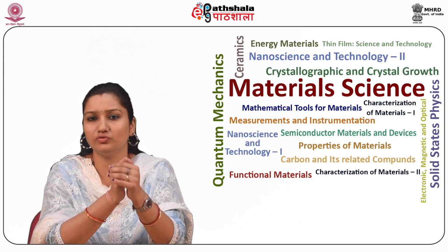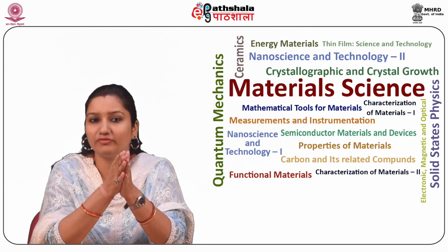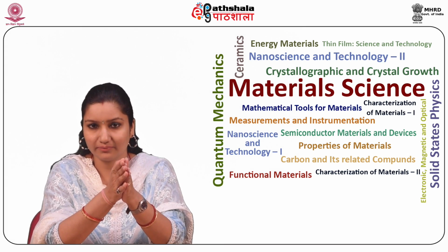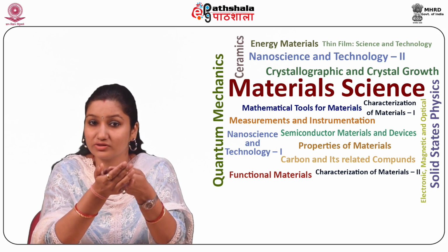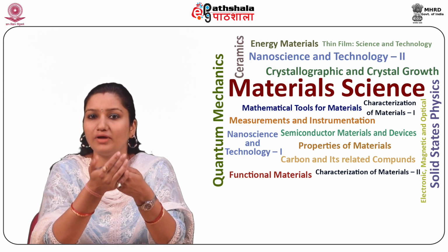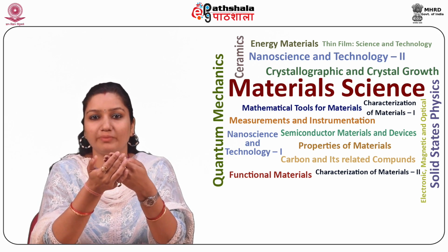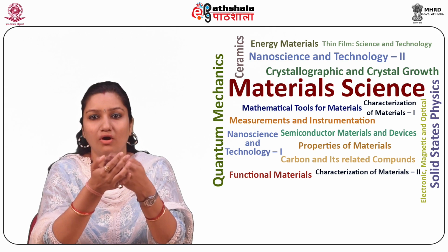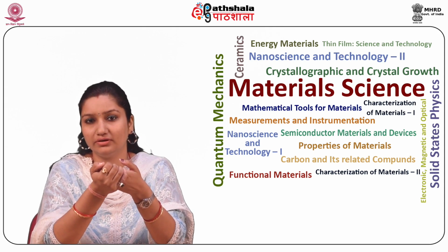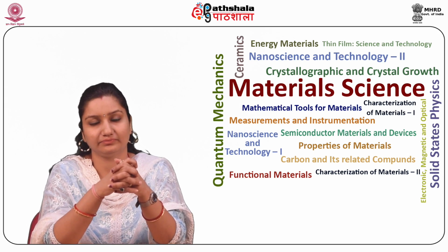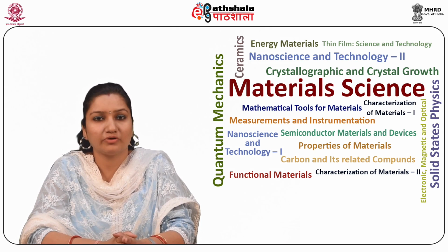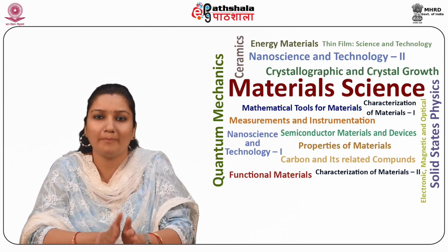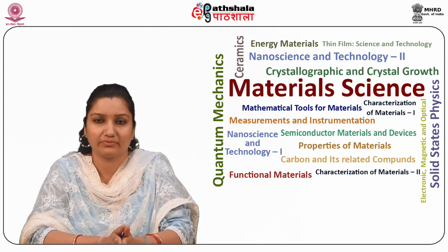In order to produce stoichiometric thin films, that is, without changing the composition of the original material from the target, the sputtering technique, a high energy fabrication method, is utilized. Sputtering is also effective in producing non-porous compact films.